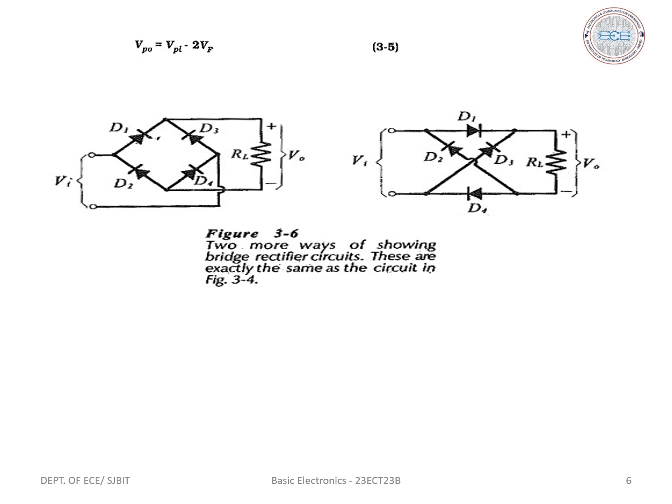When the diodes are in their non-conducting states, when they are not conducting, the time required for the capacitor to charge to the maximum level is determined by the charging circuit time constant. As I've already told for the full wave rectifier, the concept remains the same here. The time required for C1 to discharge is more. The discharge time constant is determined by the capacitor value and the load resistance RL.